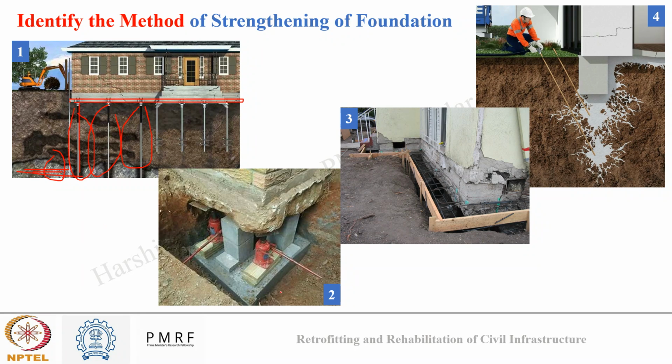In the second image, this can be the pit method of underpinning. Here you can see a pit was dug across from all the sides of the existing footing, and a new concrete footing was provided, and it was connected to the existing footing. From the sides, it was supported also, and then this will be filled with the concrete overlay to cover the whole pit.